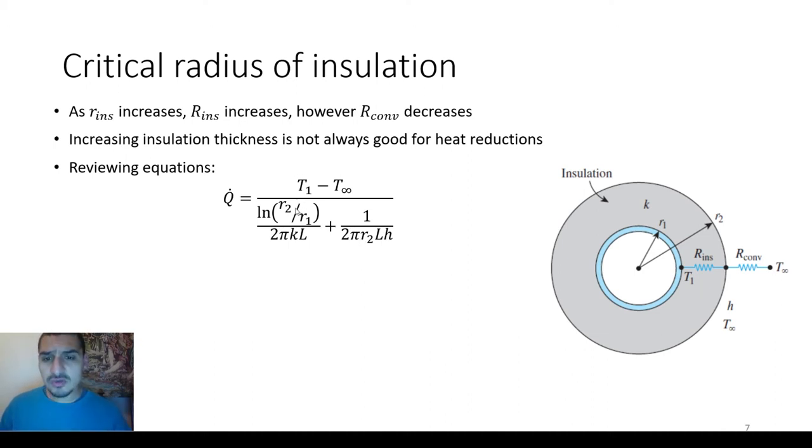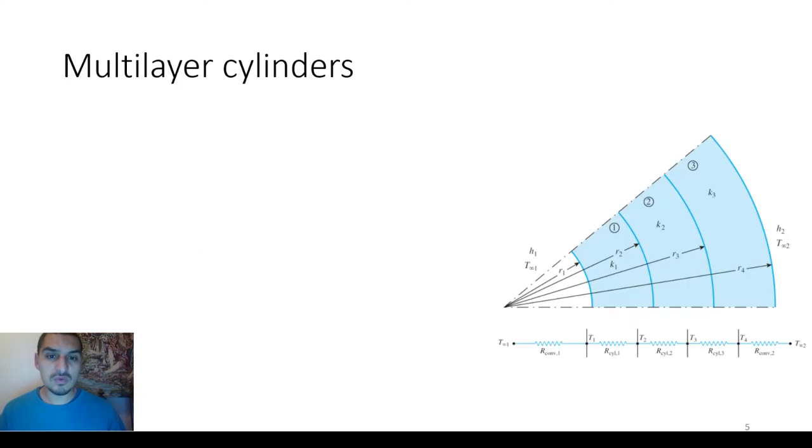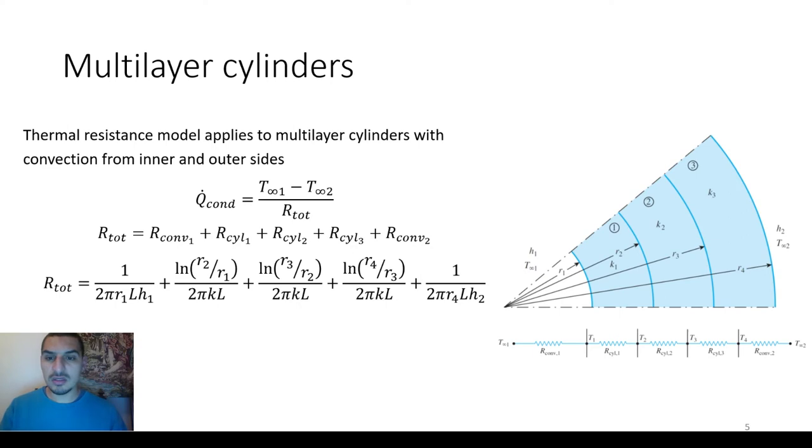And that's why R2 will have different effects on both parts of the resistance to heat transfer. That's why we need to know what we call the critical radius, which is the radius that would give the minimum resistance, so that we avoid picking this radius specifically. So we will do this here on, oops, I'm sorry.